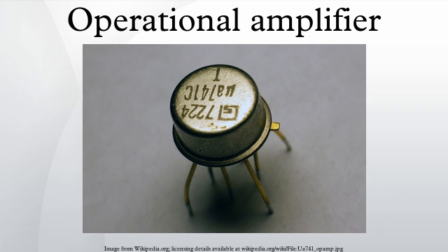This standing current in the output transistors establishes the output stage in Class AB operation and reduces the crossover distortion of this stage. Small signal differential mode. A small differential input voltage signal gives rise, through multiple stages of current amplification, to a much larger voltage signal on output. Input impedance. Because Q1 and Q3 form a Darlington pair, the small signal differential input impedance is of